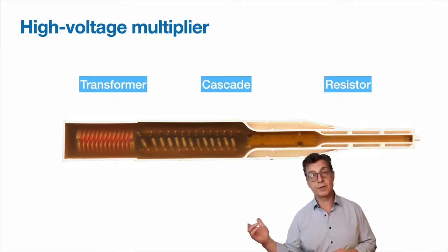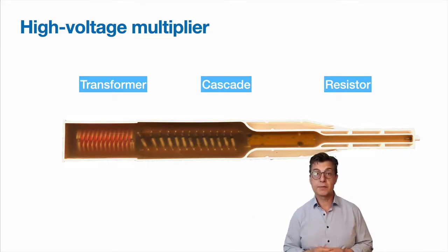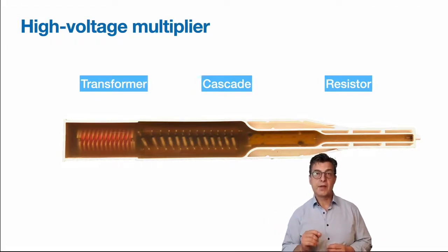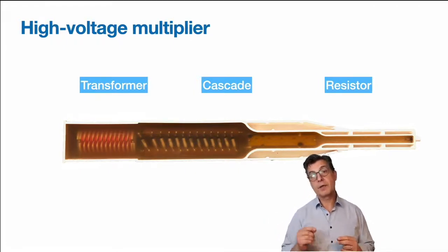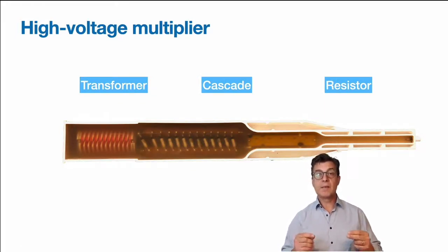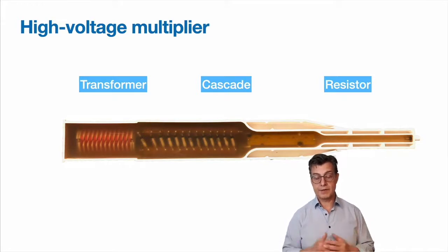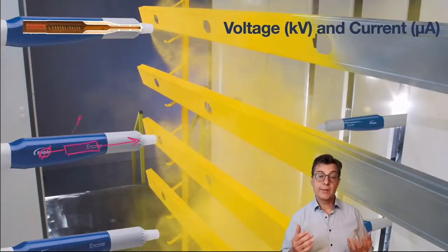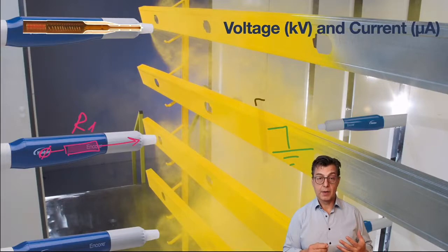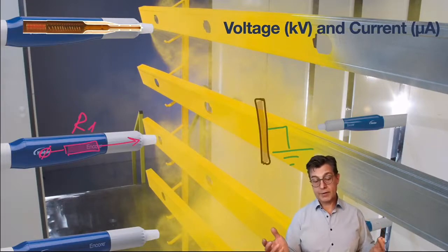Before that voltage gets to the charging electrode of a spray gun, it is also passed through a resistor. That resistor is there to limit the maximum current produced by the spray system and also to limit the maximum spark energy to keep it below 2 millijoules required by safety regulations in order to ensure the fire safety of the system. We can illustrate what is happening in the typical powder coating system by drawing a simple electric circuit.